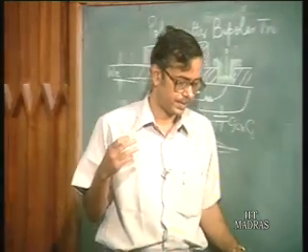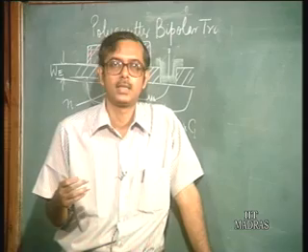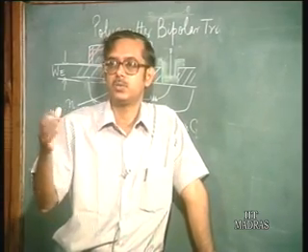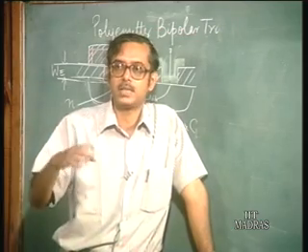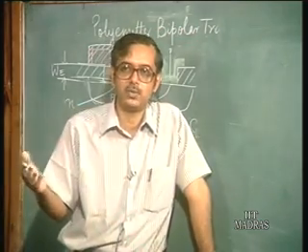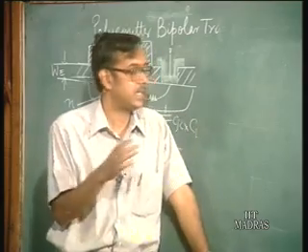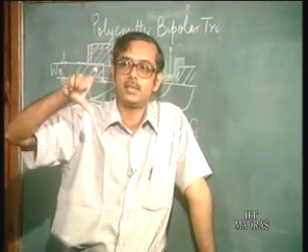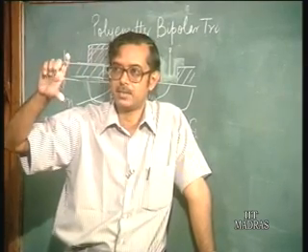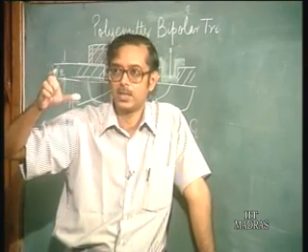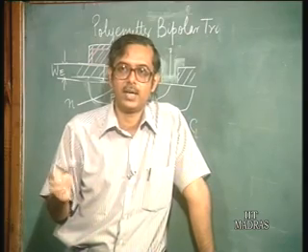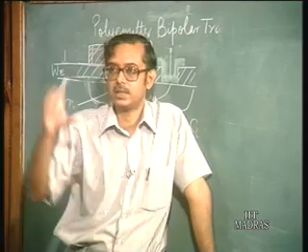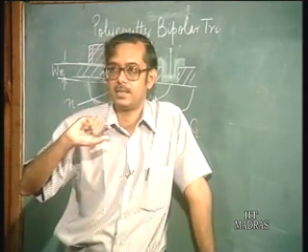See, we have always said in our discussion that I naught into R is, say, V on. Sometimes we said I naught into R is 500 millivolts, because I naught into R in an ECL gate, that is the current source value into the load resistance, is the logic swing, the amount by which the output voltage changes. And we have never said how to choose I naught and R. What is important is the drop across the collector resistance.